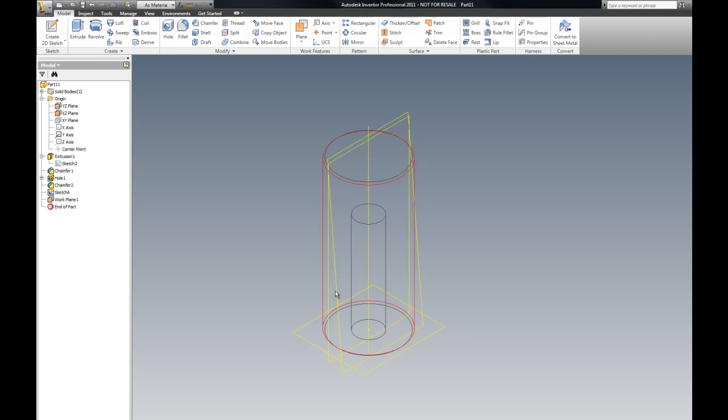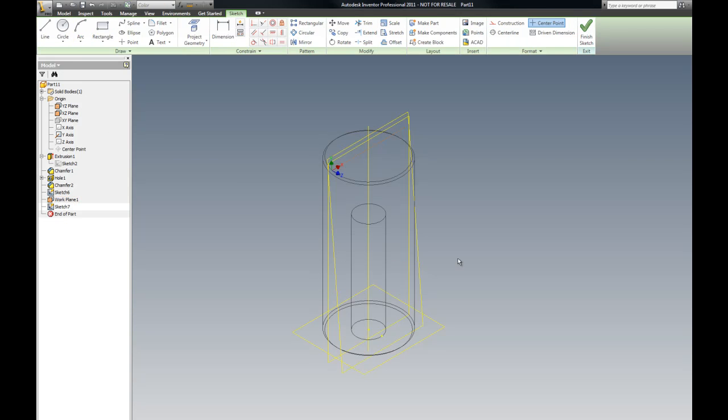So now I have this new plane here. Okay, so first thing I'm going to do is right click, new sketch. I'm going to pick this plane here. Okay, and then I'm going to project this geometry here, which is my line, and you can see there it goes. Then I'm going to go circle. Okay, going to pick, oops, should be picking off of this plane here. Okay, there we go. And that is 0.5 if I remember right.